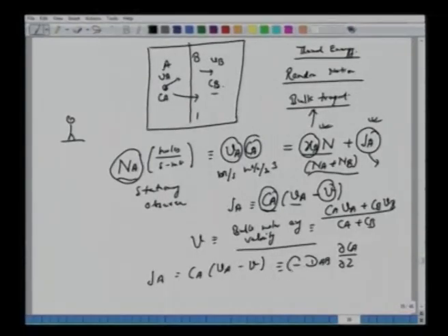Why the minus sign? It signifies that the gradient is negative. Species transport diffuses from high concentration level to low concentration level, so we have this negative gradient. But more important here is the fundamental understanding of this molecular diffusion as distinct from bulk transport. A species gets transported because of concentration difference. This can exist irrespective of whether there is a pressure drop or no pressure drop. So there is a concentration gradient, Fick's first law.